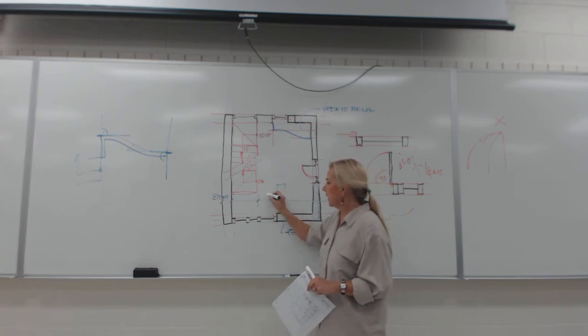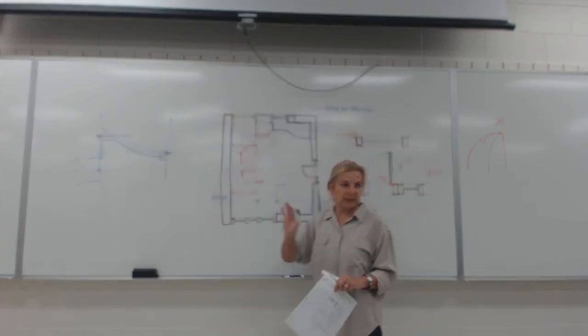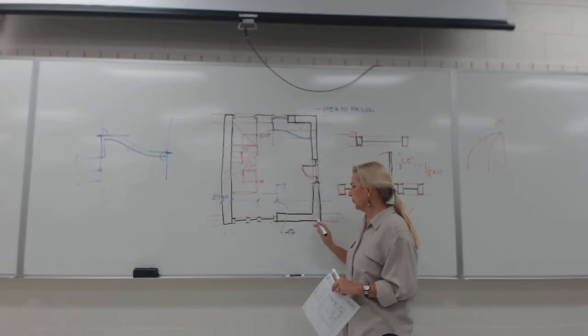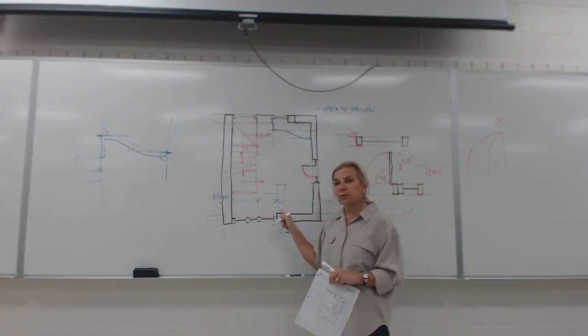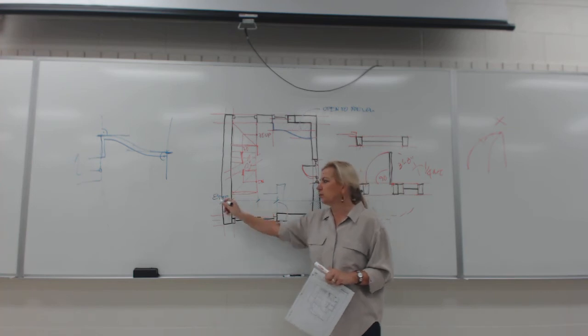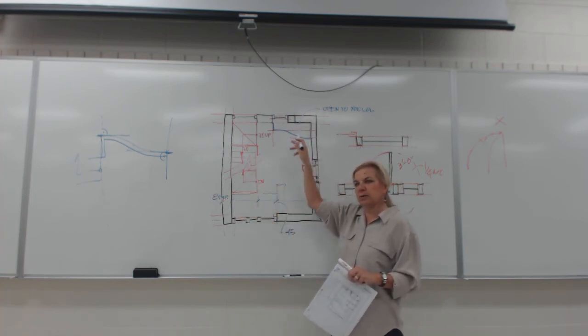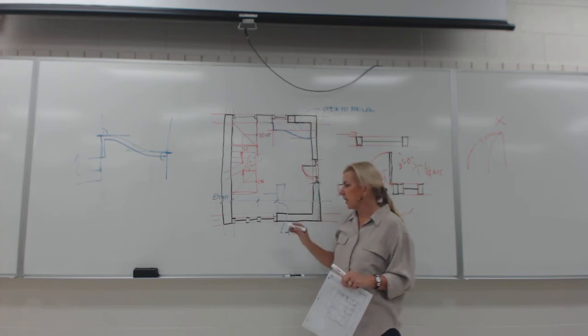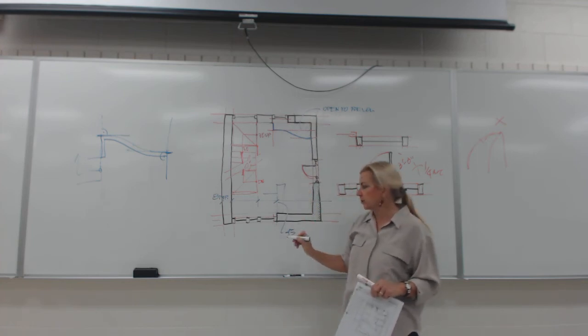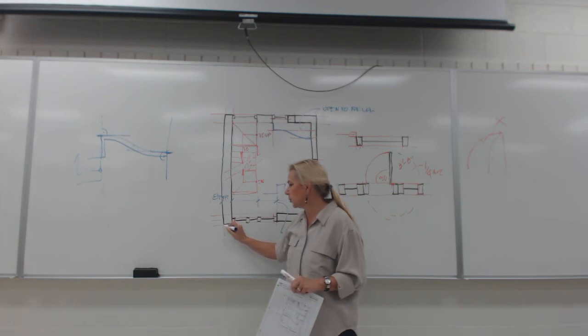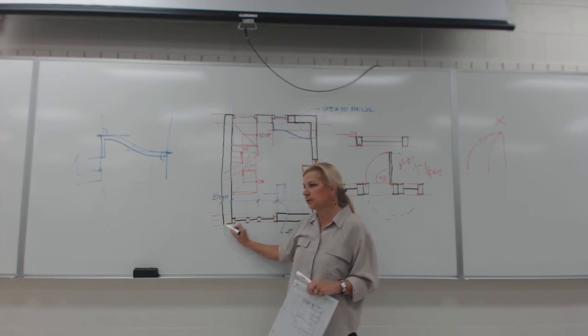We're going to do 2 guidelines. That is already covered. We know how to do dimensions beautifully. But what you don't know is that these dimensions need to be continuous strings. Maybe a couple continuous strings in each dimension on the inside. On the outside, the convention for houses is you don't go with the dimension line right to this point.